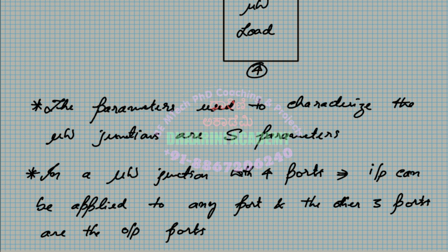So when I give input to one port, I have all these things happen. If I write that particular measurement as a row of a matrix, I give a certain amount of energy, something comes back to the same port, something goes to the second, something to the third, something to the fourth. So when I write one row, I have four different options.